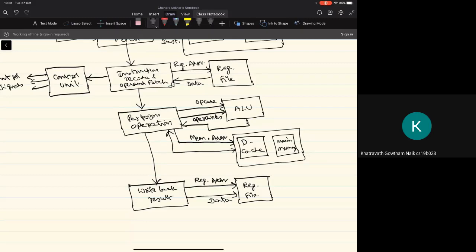What we are interested in is whether the arithmetic and logic unit can complete the operation within one clock cycle period or not. If it is a 1 nanosecond clock period, it all depends on the propagation delay of a logic gate and how many tau it will take to complete the necessary operation.